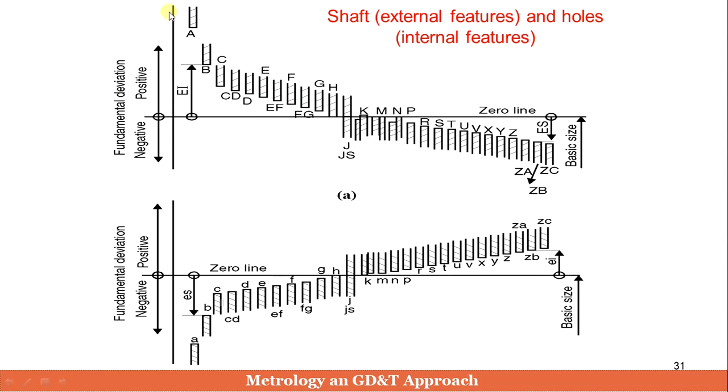So what does this represent? The y-axis is the fundamental deviation, and the x-axis represents the zero line. In this case, the portion above the zero line is always positive and below the zero line is always negative.